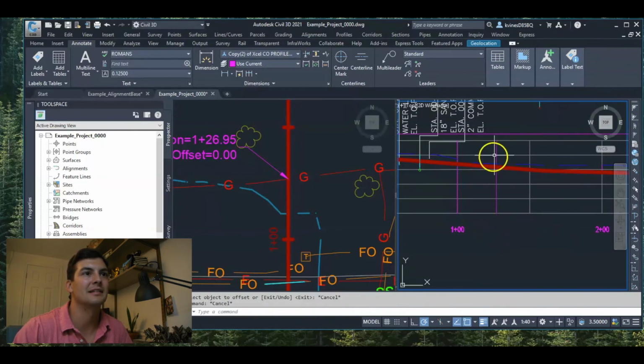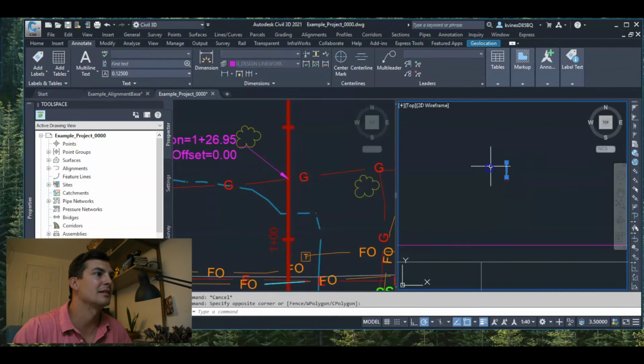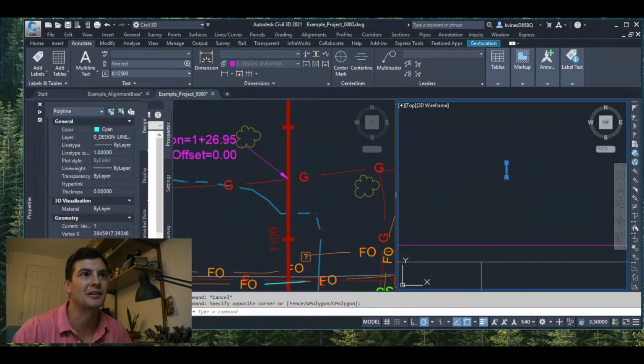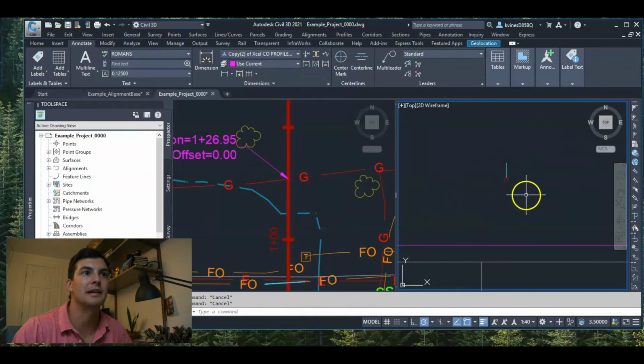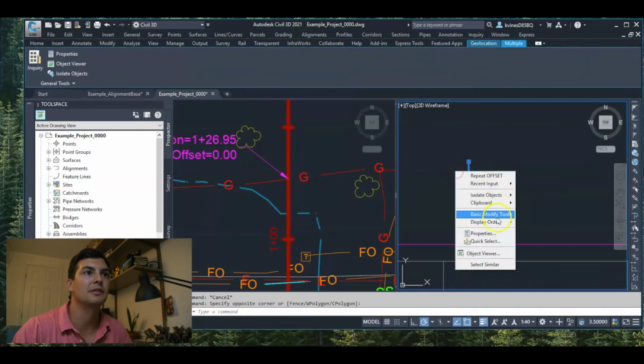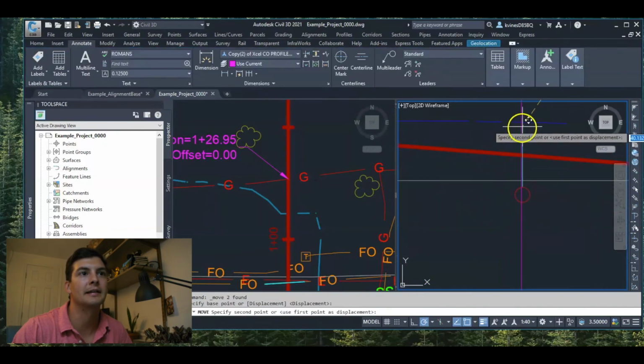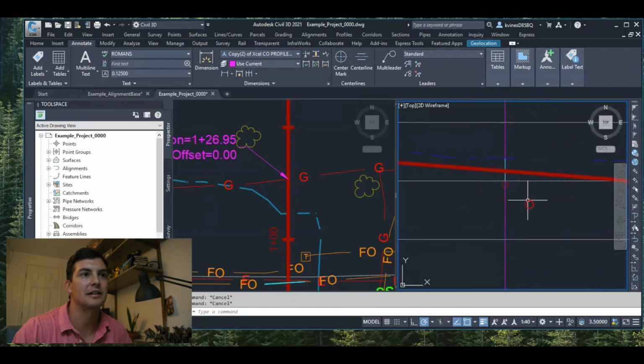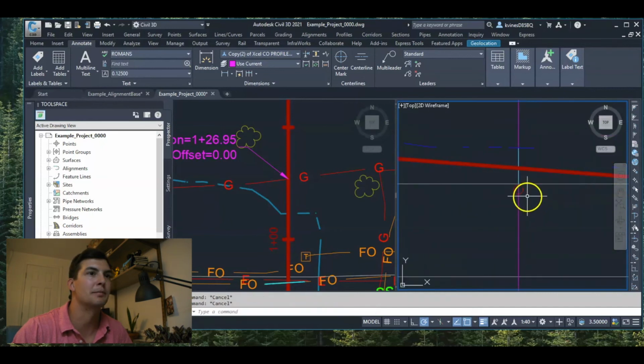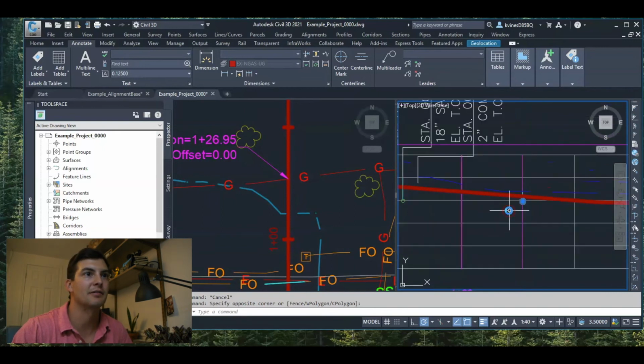And then this is, I'm assuming, going to be 4 feet because that is our assumed depth before we get potholes. And we're going to move this 4 feet below grade at that stationing number. And that is our pipe size, typical before we get information from the surveying company again.